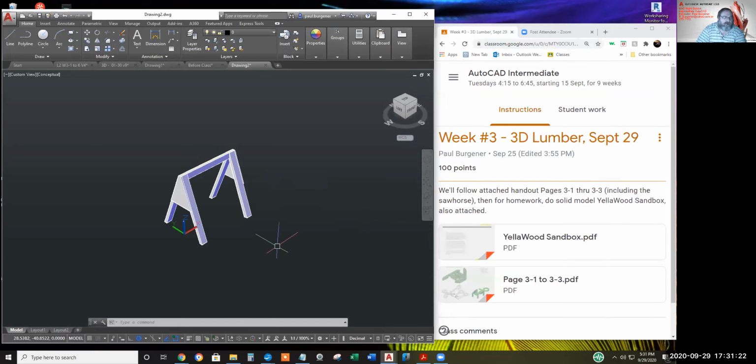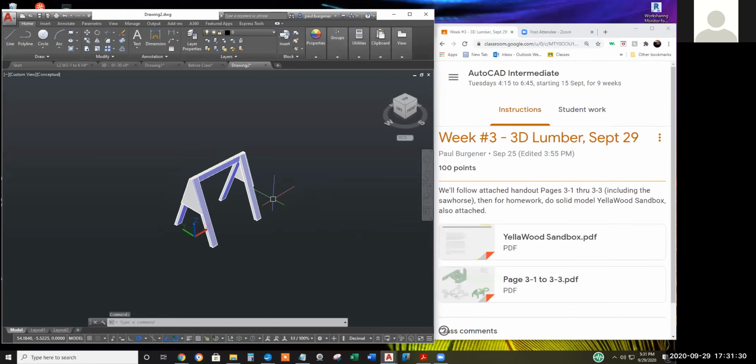Anybody got questions one-on-one while we're waiting? The question I have, Paul, on right when you started with the 2x4 lumber, instead of like 3.5, wouldn't you put 3.5 divided by 12, like 0.125? Wouldn't you make it more precise, or would you just literally put in 3.5? Well, I have made the assumption that an AutoCAD unit is an inch. Okay, and you said divide by 12.